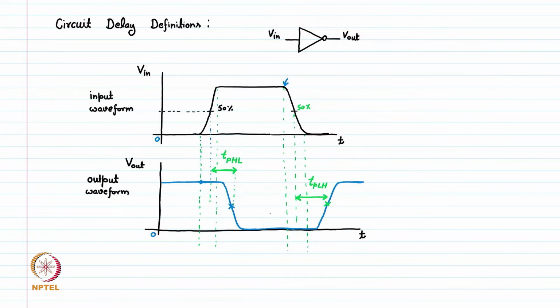This mostly depends on the PMOS sizing, how strong the PMOS is. So these two values, TPLH and TPHL, are a little different. However, we want to have them kind of the same so that we have a single delay in the rise as well as fall. However, these are slightly different.